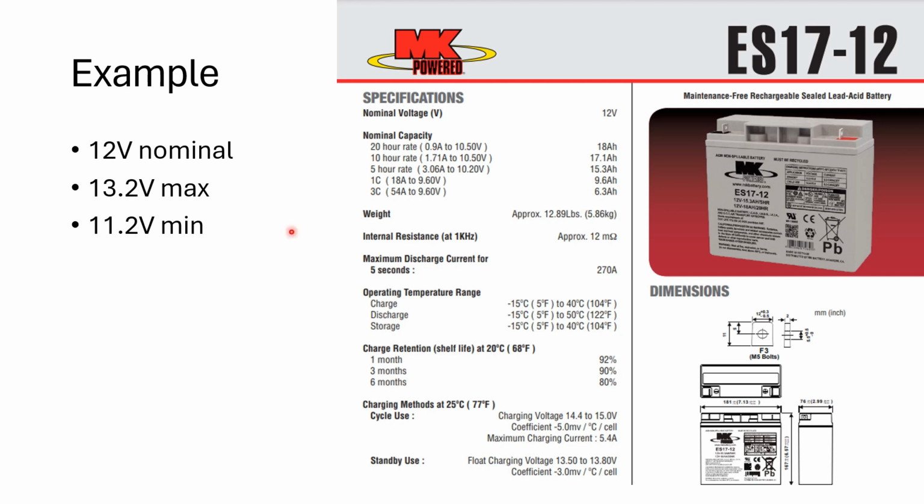So here you can see the capacity is given in amp hours. So 0.9 amps, it's about 1 amp. Let's just use that for our math. And then they're taking a fully charged battery, so assuming about 13.2, they're discharging it down to 10.5. So a lot further, about 0.7 of a volt further than we would, but we'll use this for our math anyway. So 18 amp hours.